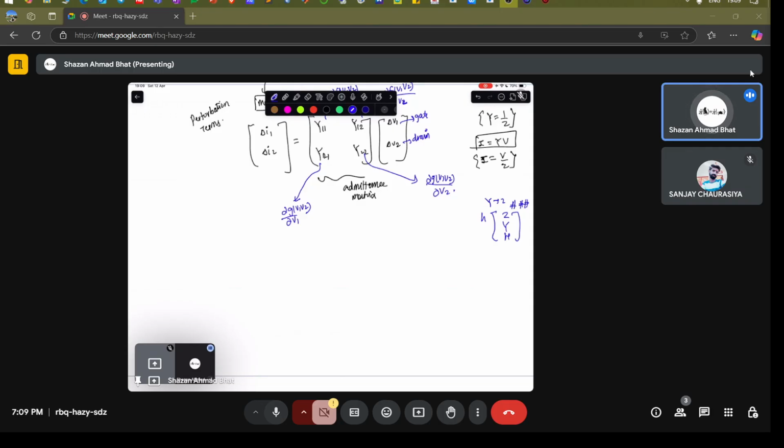You have all of those parameters in terms of the matrix forms, and you can always convert one into another. They are quite commonly asked questions in, I guess, GATE examination as well. So now you can write the equation for the small signals, for example, small I1 is equal to y11 V1 plus y12 V2. You can write I2 is equivalent to y21 V1 plus y22 V2.